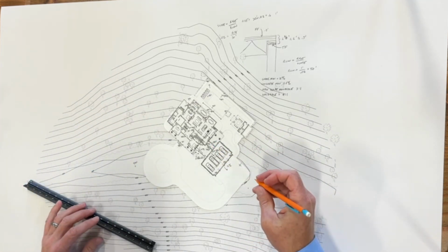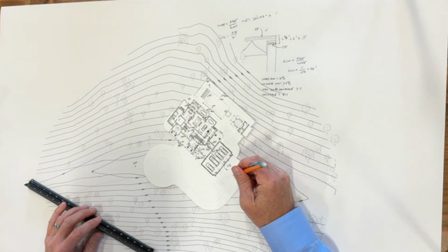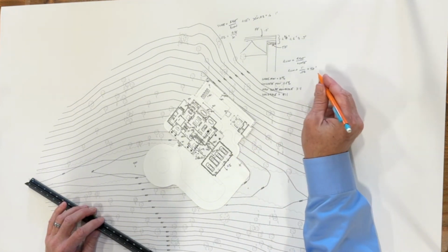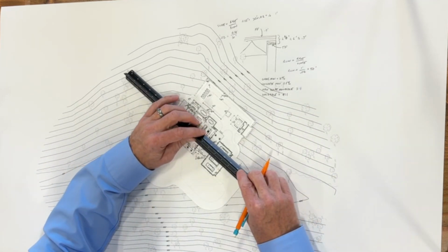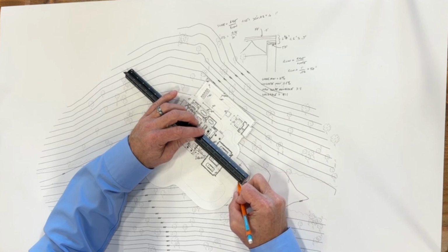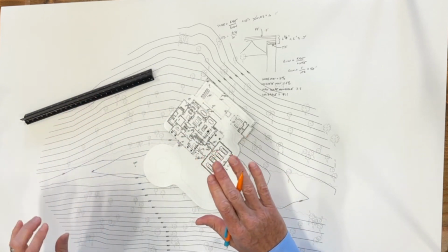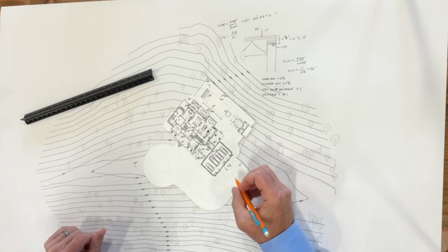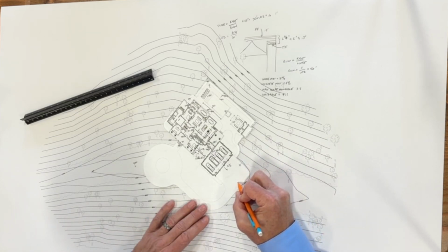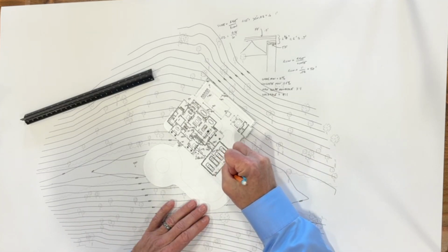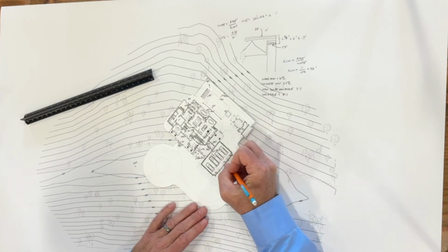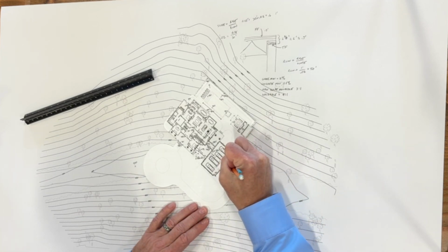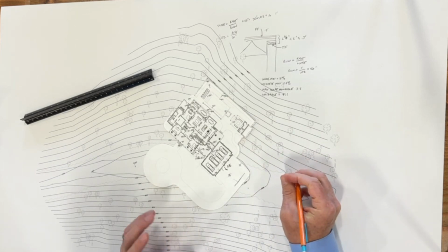So, you know, maybe we make it a 3% slope. So if it was a 3%, what's 1 divided by 0.03? 33. 33. So here's 30. That just feels better to me, to have it just be slightly more than the minimum, but not too bad because I want a nice flat driveway. So here's 33 feet, and this is what I mean. It's 33 feet from there to this spot, right? So now we draw that 940-foot contour. What we're saying is there is now a 3% slope on this driveway, which is nice and comfortable.